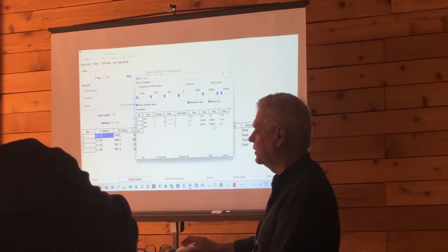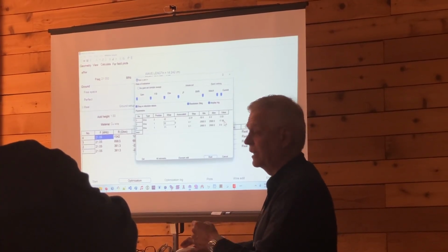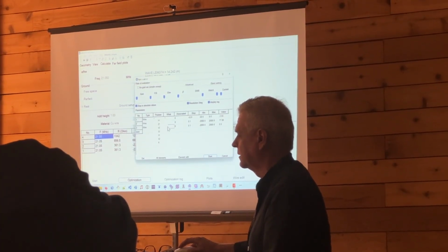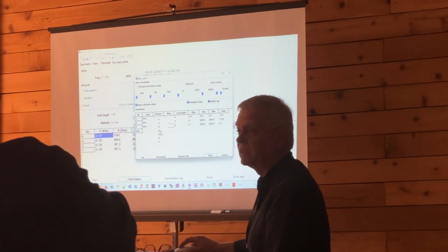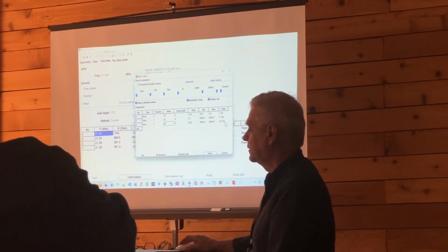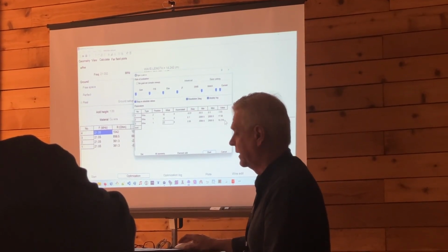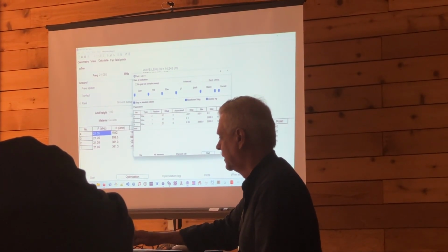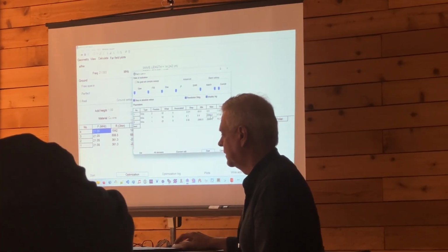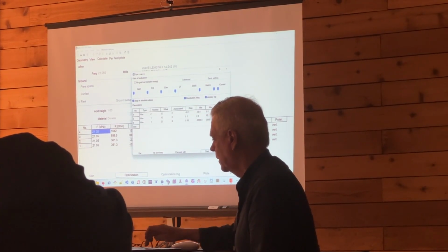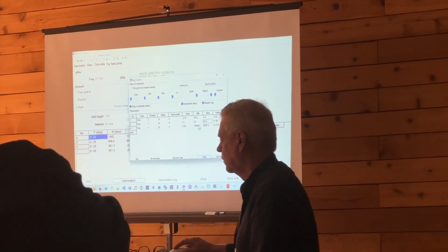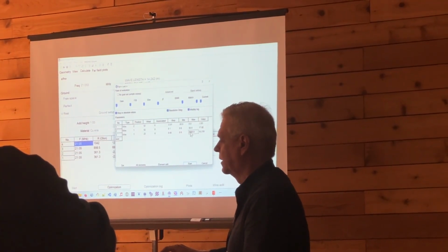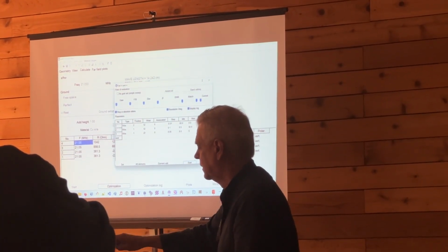As soon as we put X2 here, notice that it remembers and says, hey, right now it's at 17.68. It's a good quick check, and we're not in the wrong place. The second one is Z2. That one. And it's reminding us, hey, you've got that one set at 10.218. Fine. Again, it's going from minus 2 kilometers. Let's just put some sensible values. Go from 0 to 50 meters. We have to hit enter. I keep hitting tab there. It doesn't take it. So it's 50.